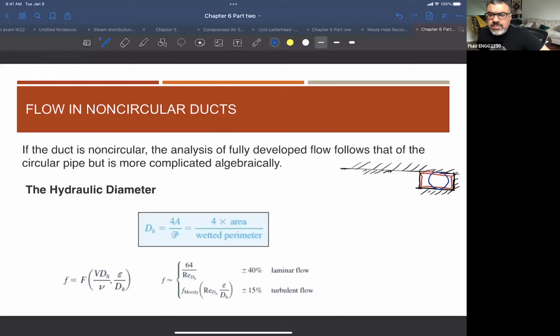Let's assume the same airflow rate. Let me just add one more restriction: same flow rate. You are buying this fan, the blower in the furnace is creating the same flow rate, right? That's the size of the furnace. Why do you want to have a bigger area for the same airflow rate? Less velocity. And what is less velocity creating?